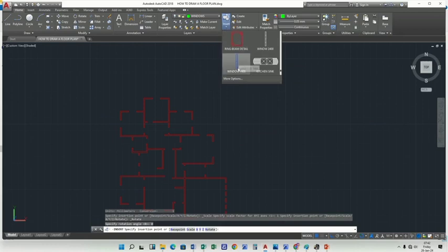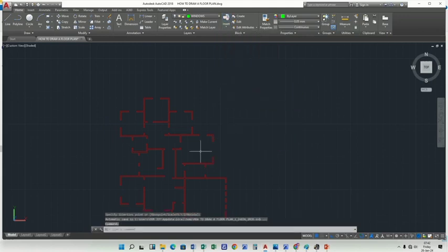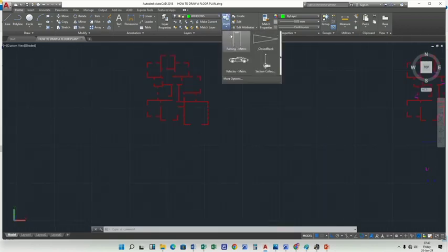It cannot show, but I've clicked, and it's not showing. Why? Because the layer is off. So let me switch on the layer. Let me try from the car. I've clicked there, it's not showing. What's the problem? The problem is the layers are off. So let's see, I try with another one.